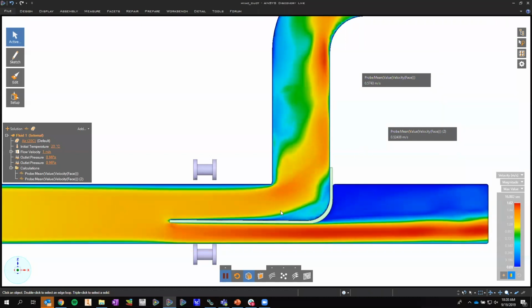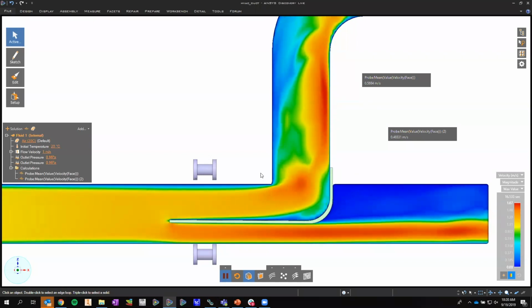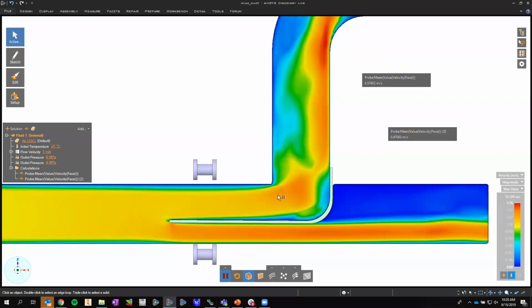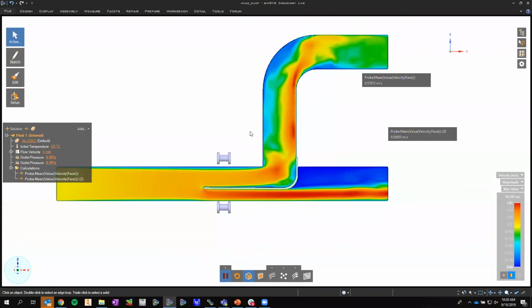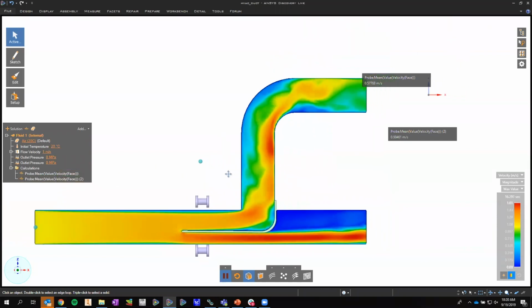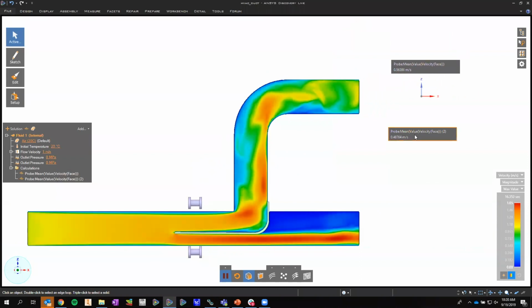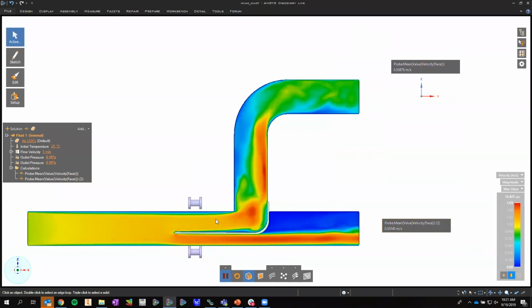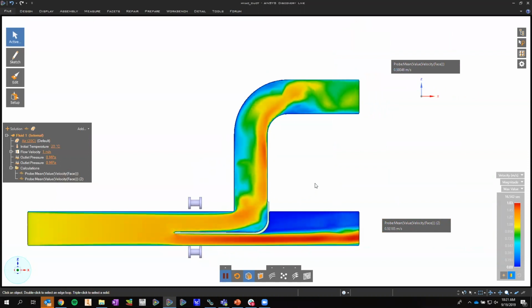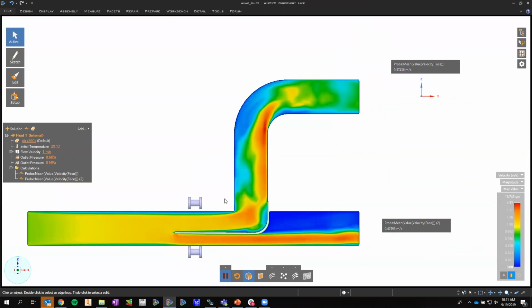Exactly. This model maintains a live link to the Inventor model. So if the Inventor model updates, you can have that propagate down to the Discovery model, which is really cool. Something similar to some of the functionality in some of the Autodesk products. But as you can see, JD just made a simple change to that baffle, adding a radius to it, using some of the direct edit features within Discovery. Boom, you instantly see the changes he makes, and he can change the size of that radius, move it around, and so on, and you get some instant gratification as to what your simulation is, or what it's going to do in real life if you actually apply this change.